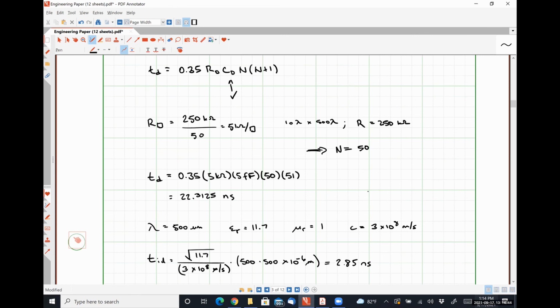The sheet resistance of your metal layers, which we'll talk about probably later next week, is usually on the order of less than an ohm per square. So you can see why the RC delay goes way down when the R value goes way down, and the ability of the material to propagate your signal becomes much more important.